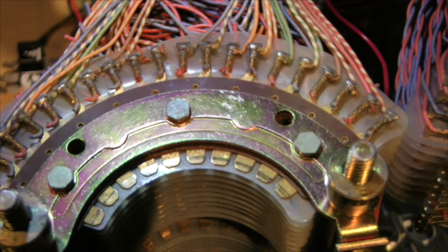On every level, the top side and bottom side terminals are given rotary position numbers, which from left to right are 1, 2, 3, 4, 5, 6, 7, 8, 9, and 0. For any given line circuit, its tip, ring, and sleeve terminals are always in alignment in terms of their level number and their rotary position number.